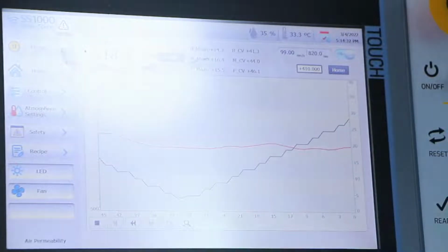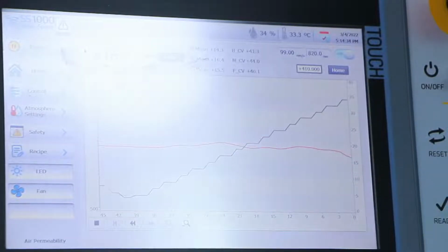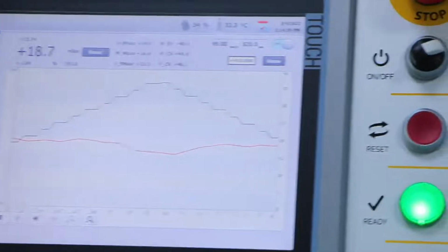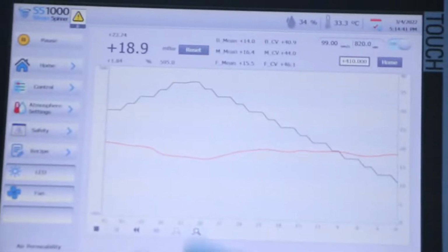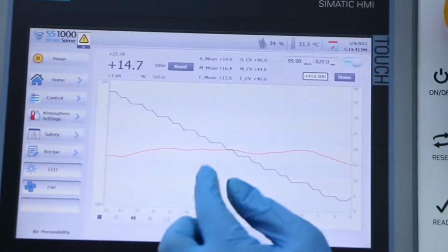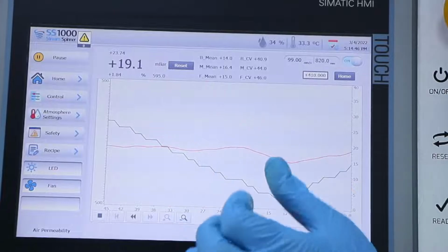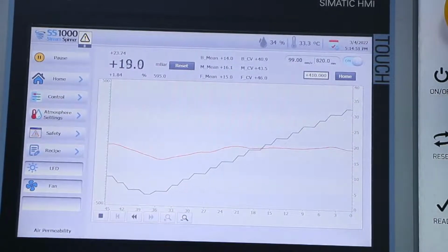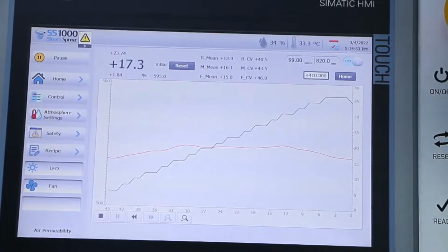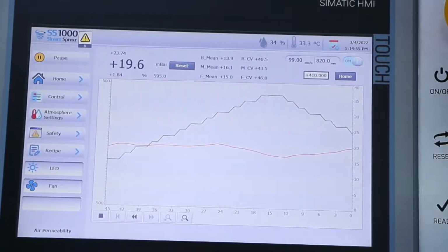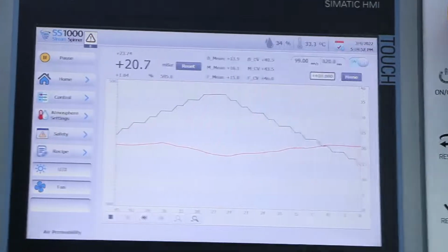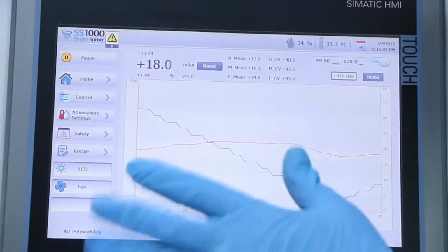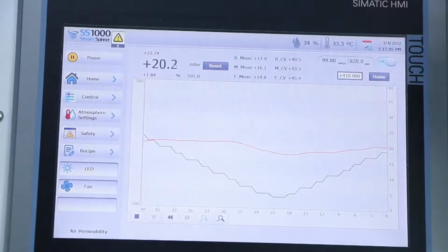Of course, it's not possible to have a perfect straight line for your thin spinning, but you can see that it alternates very closely, it's not a big difference. So this is actually good for us. This indicates there's better distribution of the nanofibers, and they're being well made across the width of the substrate roll. You can see right here it's changing from 18 to 20, 23. So the midpoint would be 20